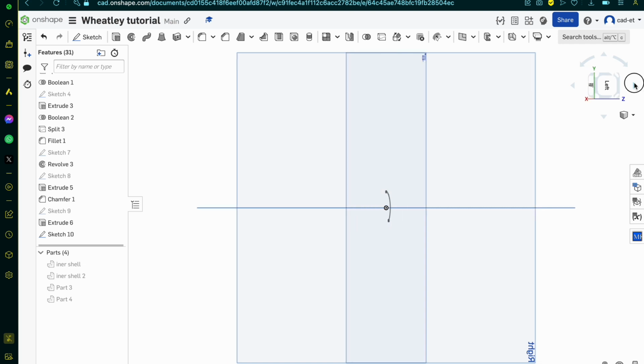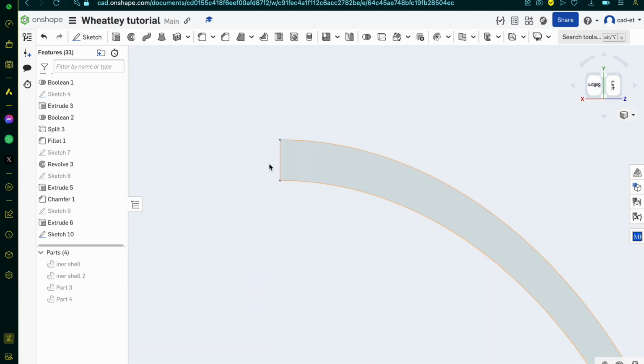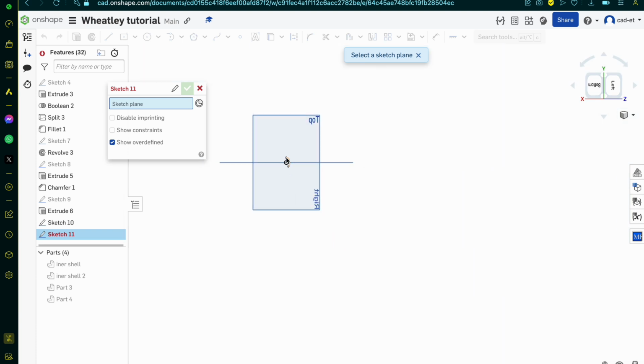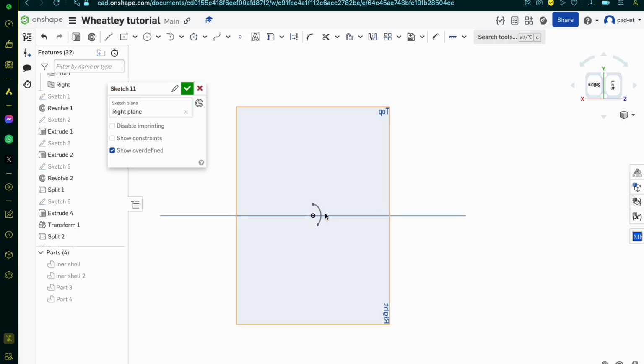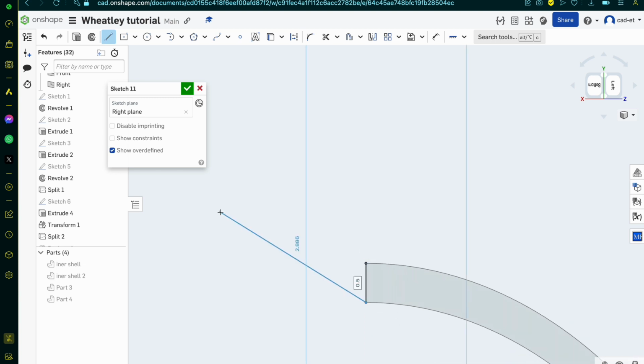Right, so bring it back round. Use these arrows. I can bring it into a point where I can now work on this. So what I'm going to do is bring up a sketch. I'll do a sketch on the top axis. I'll draw a line here, escape, and put in a rectangle. So restraint here, it has 0.5. We only want this to be 1.